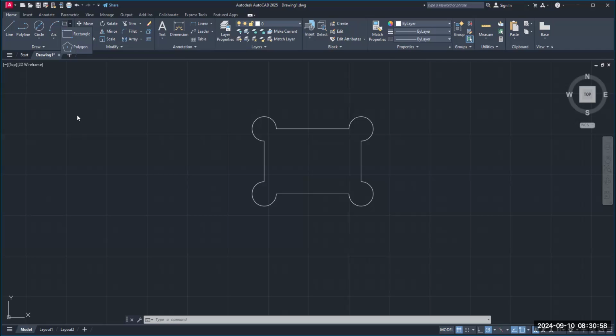All right. Do me a favor, just click on polygon for a minute. Click on polygon and click anywhere on your screen. It doesn't matter where. Well, actually, before, let me hit the escape. I'm sorry, let me try this again. Hit the escape. Sometimes it doesn't take. I'm going to click on polygon, and it's asking me first to enter the number of sides I want. You have to follow your menu, what it says to do. It says 4, you want 5, you could want 6, not 56.